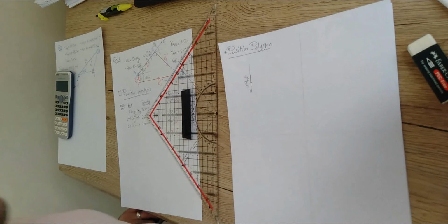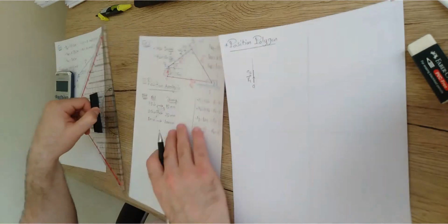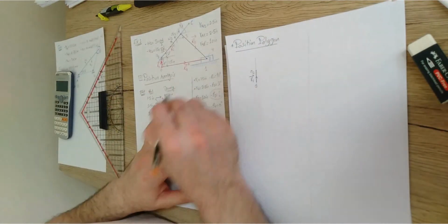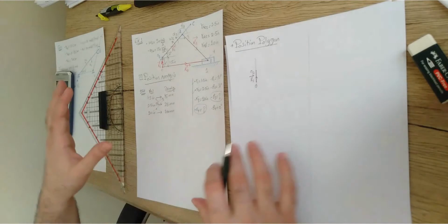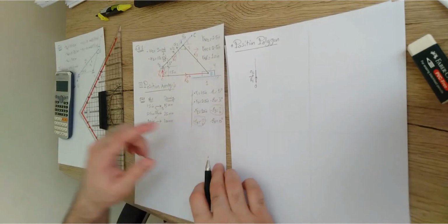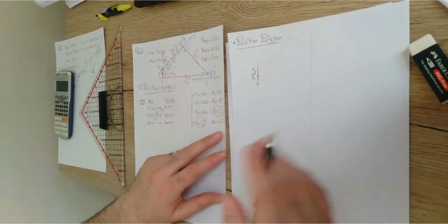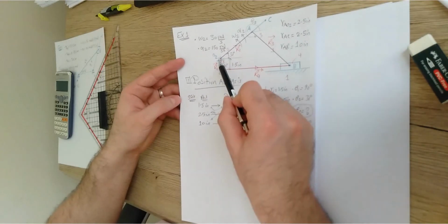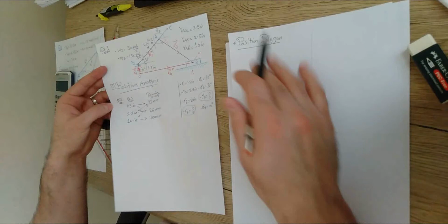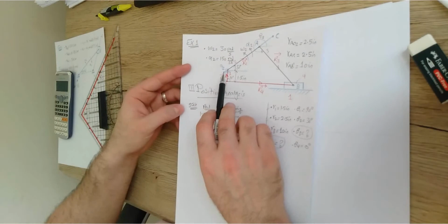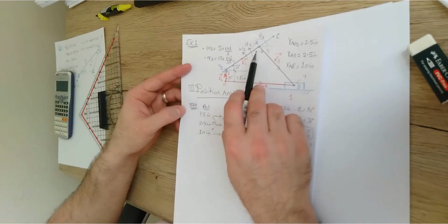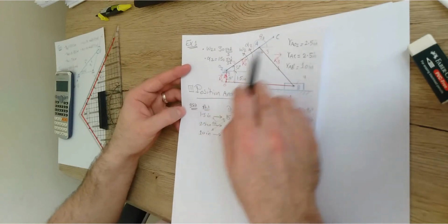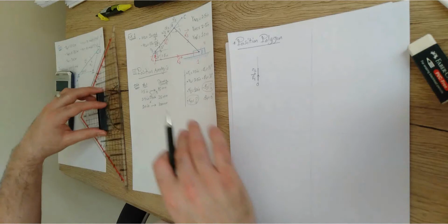Now let us move to the next one. We got this R1. Now we're going to move to R2. R2 is also fully defined. It has an angle of 30 degrees, so we have to measure the angle first. But you should understand that this position vector is set up between 2 points, point O2 and point A. In this polygon, we do have so far just point O2. We have no clue where point A is. So from point O2, I'm going to draw this position vector with an angle of 30 degrees.